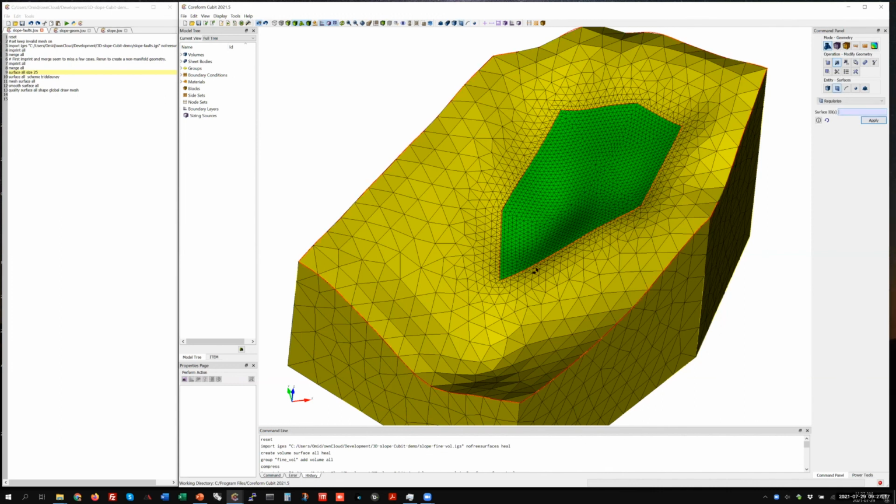So that is usually how I would do it. I'll start doing things graphically, then I head to the history tab here at the bottom on the command line, or you could also do it here, but here there are some other prints and communication with the user. Then I will paste it here, and then play the macro or the journal file. You could play the whole thing, or if you're just playing with certain areas, let's say you don't want to smooth or look at the quality, you can just select the sections you want to play, right click and play selected.